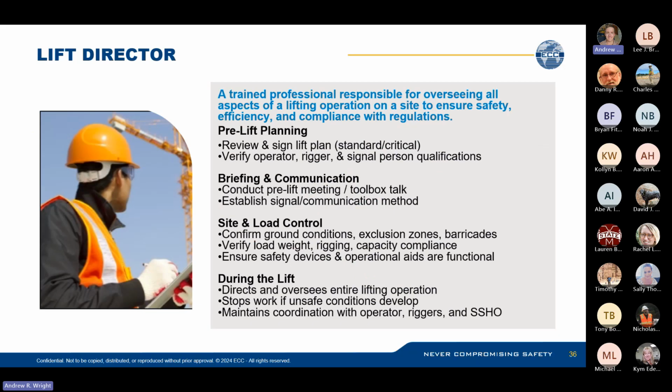The next role is the lift director, or sometimes referred to as a lift supervisor. This is a trained professional who is responsible for overseeing all aspects of a lifting operation on site to ensure safety, efficiency, and compliance with the regulations. They're going to be involved with the pre-lift planning. They're going to review and sign the lift plan, standard or critical plan, verify operator, rigger, and signal person qualifications, briefing and communication.